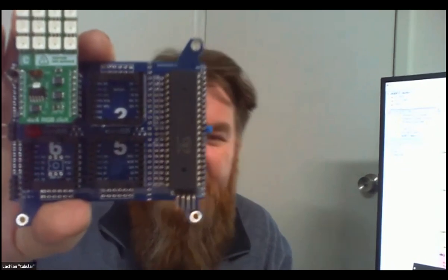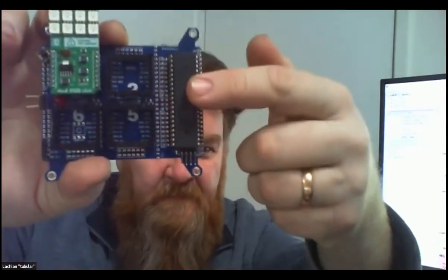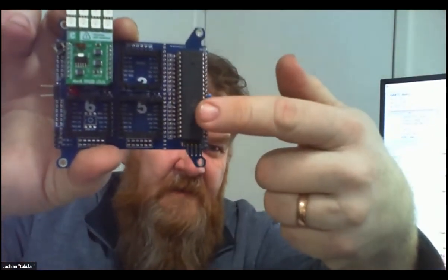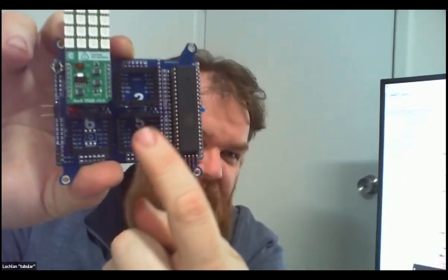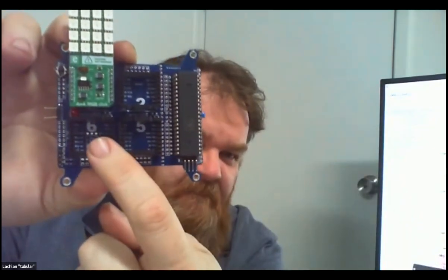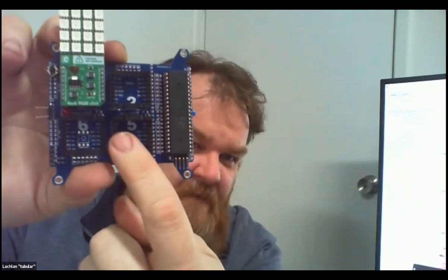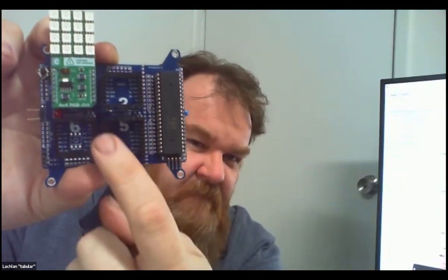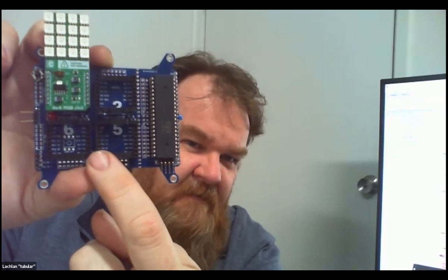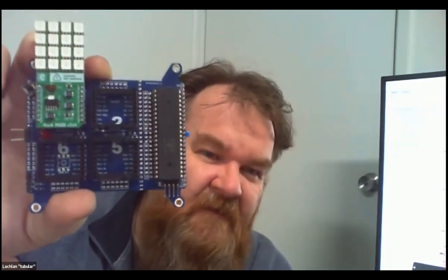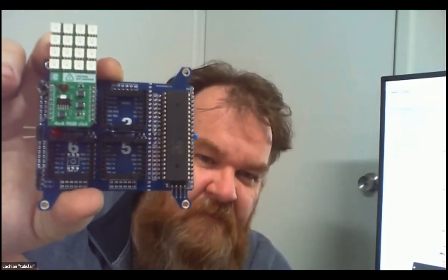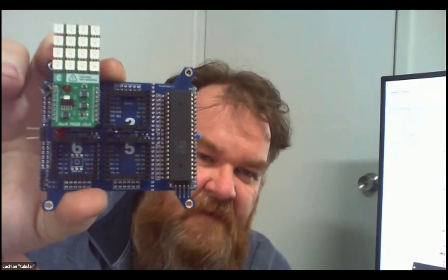Yeah, I mean, really, there's always a CPU across on this side, whether it's a P1 or a P2. And for every I/O pin, it's just bringing it across to a Clic socket, which is usually one-to-one mapped to Clic sockets 1 through to 4, and then 1 through to 5, and then Clic socket 6 is in parallel with Clic socket 5, which makes it useful if you're doing, say, I2C or maybe SPI or something like that.